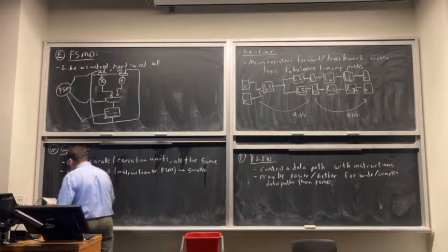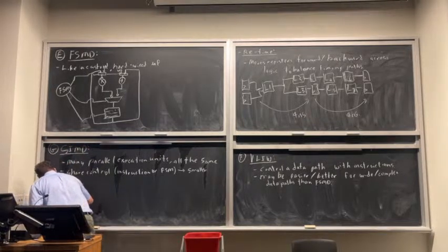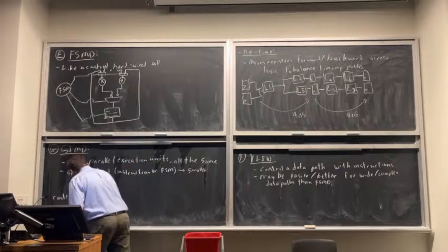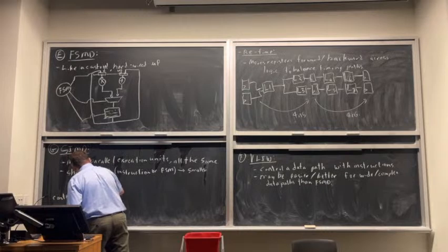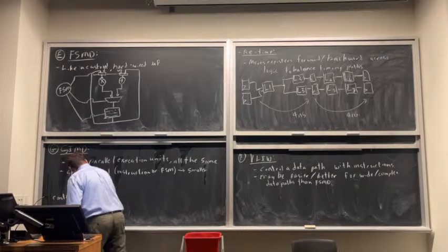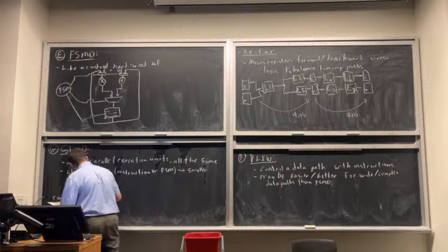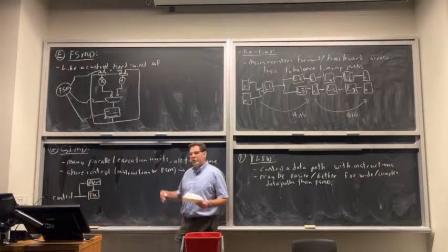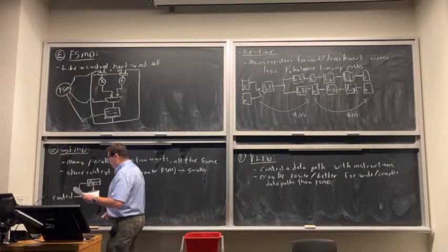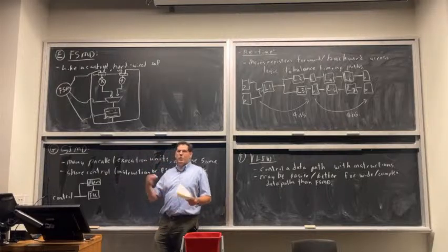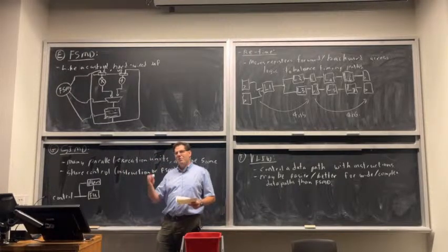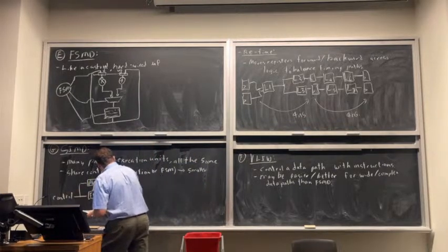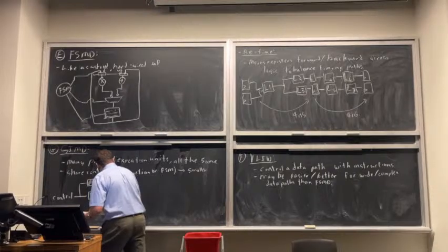So let's see what this looks like. So here's my control logic. Could be instructions, could be a finite state machine. And I've got some functional unit. I've got some memory feeding it. So I could just control these with one instruction stream or one FSM. But if I figure out my computation has a lot of parallelism, it's working a lot of vectors, for example, and we tend to do the same thing to the first vector element as the second vector element as the third vector element, then I could say, well, let's make a few of these compute units.